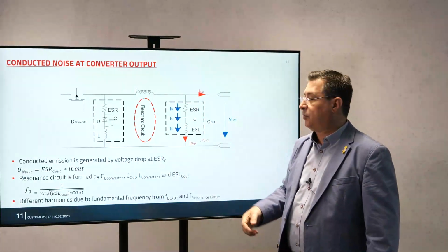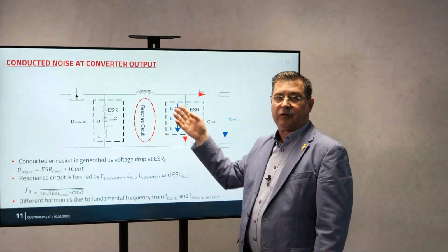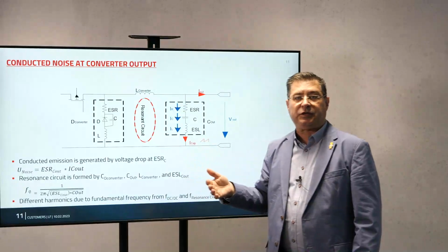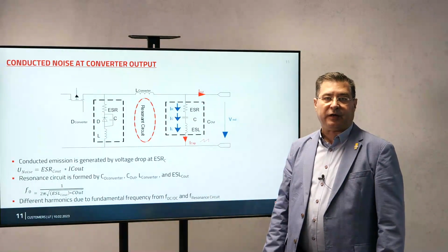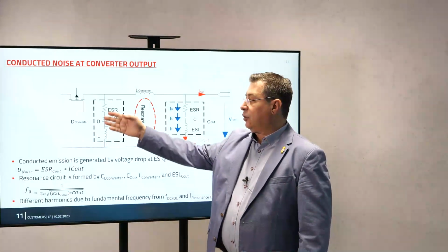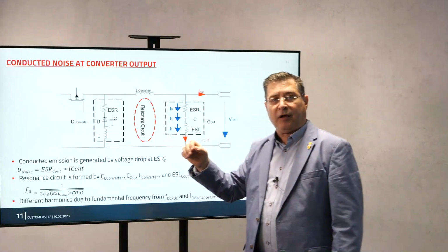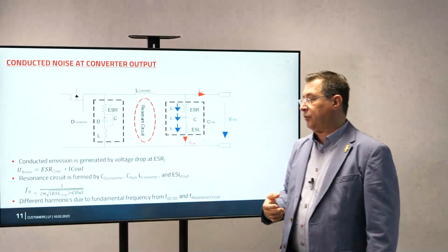The inductor has parasitic components. And at very high frequency, it can oscillate here and start to make a ringing, which in the EMC lab can be seen with a receiver, and you can see that you make noise. So try to use maybe a synchronous buck converter to emulate the ideal diode, and try to keep this as short as possible to not have any resonant points.